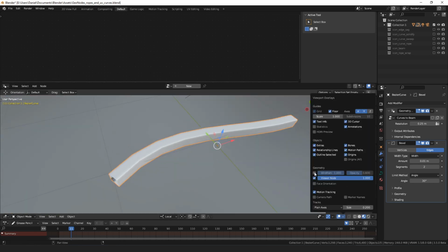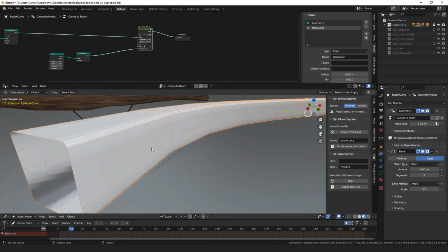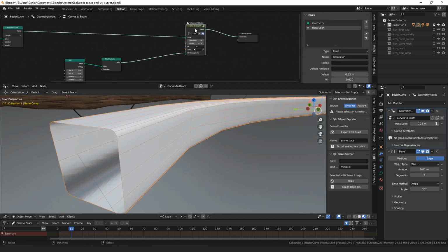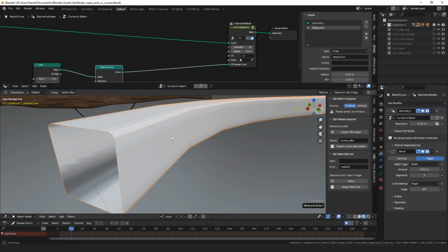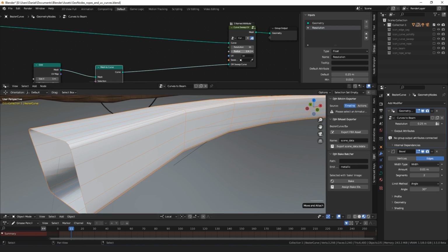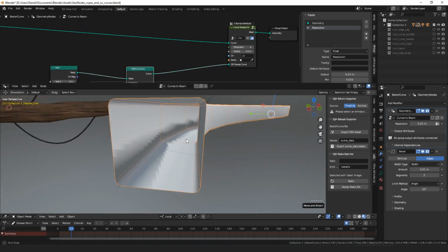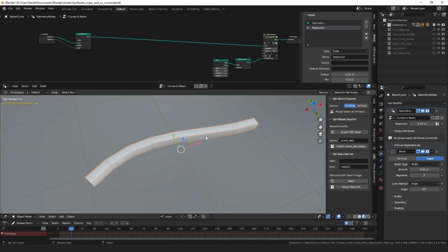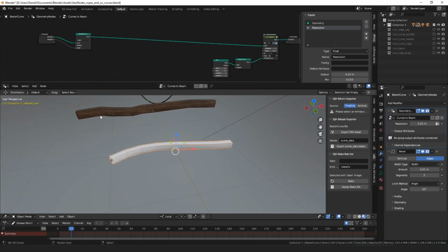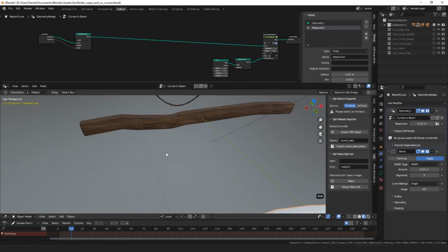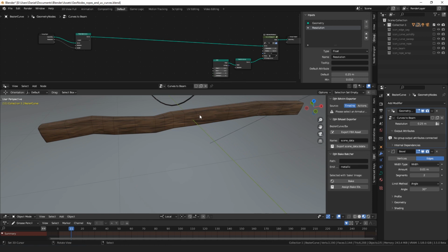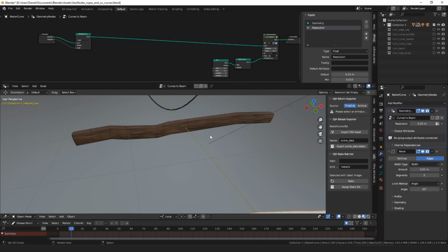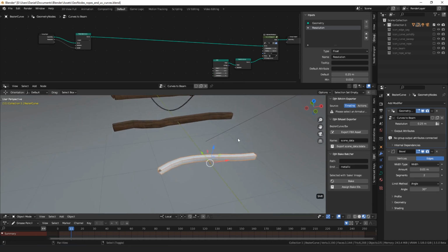Let's turn the wireframe on. Now, interestingly, because the sweep curve resamples, the current version of it anyway, we have more edges than we actually need. So since we have 4 in our grid, we can set the resolution to 4 here. What I did on the mesh version is I resampled to a resolution, and then I deleted some of the points randomly so that you got different spacings between the edge loops, which kind of breaks up the uniformity of the noise.